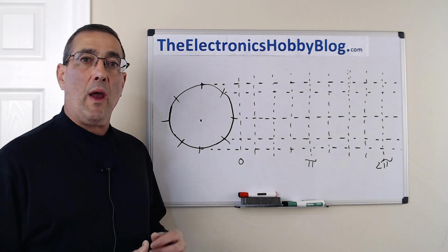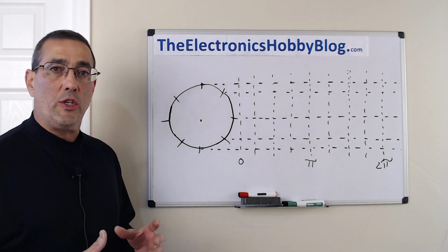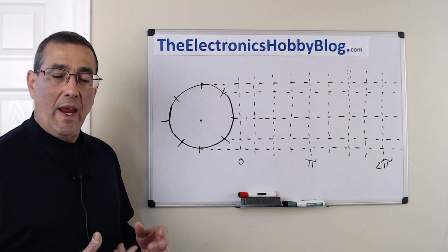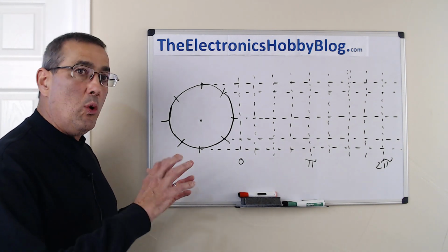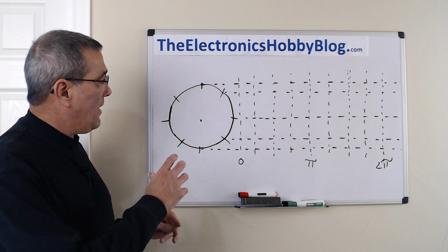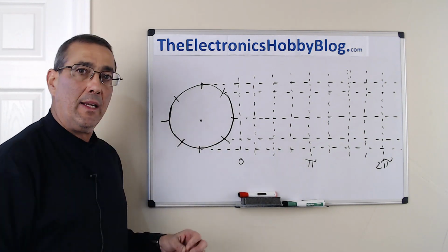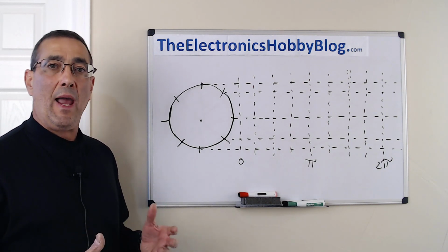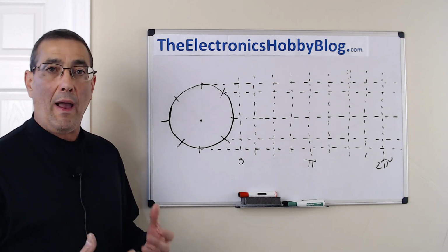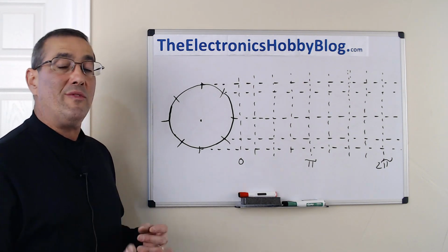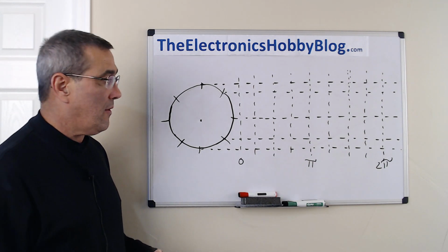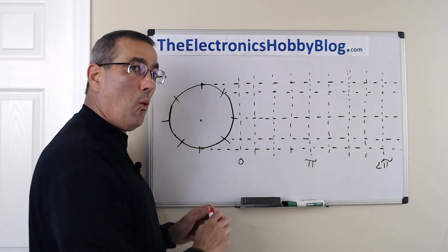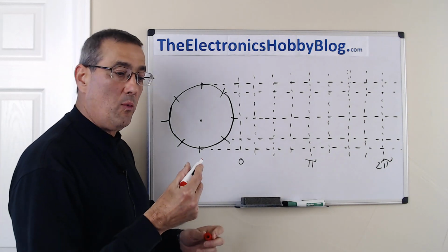And as that generator moves, there's an armature that includes wire windings around the armature that move through magnets. And as the winding moves into the magnet, it starts to generate electricity. And the more fully it moves into the magnetic field, then the more electricity it generates. And as it moves out of the magnetic field, it generates less. So let's look at how that works and why that means we get a sine wave.